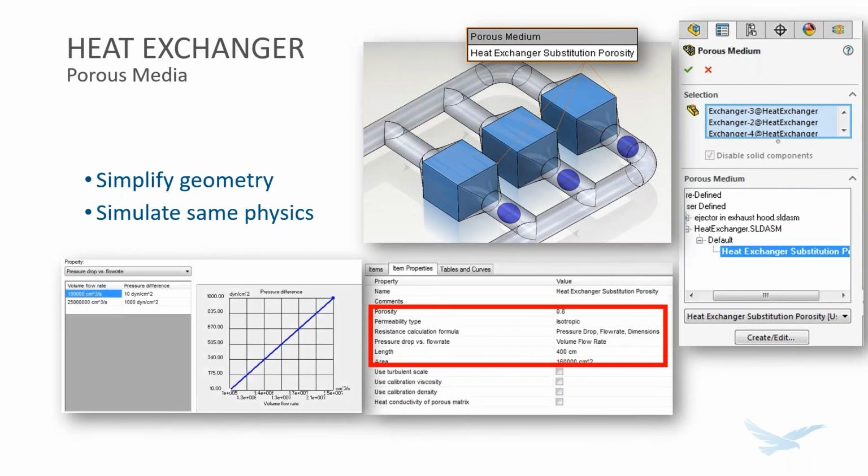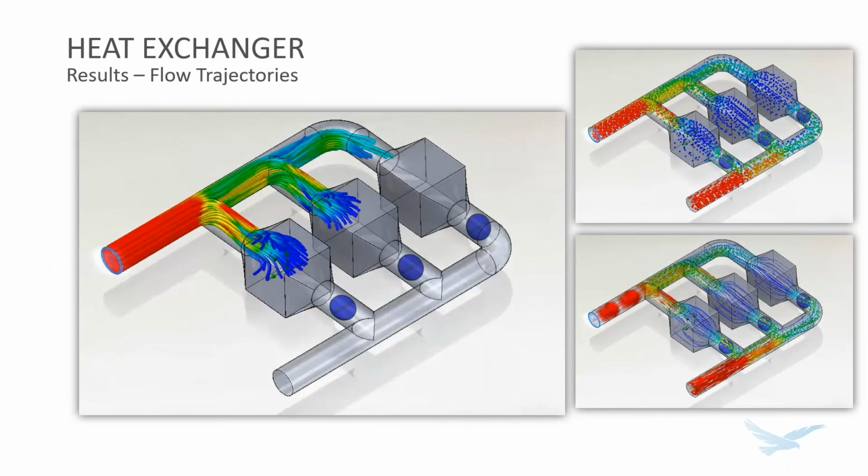So you've got an extensive engineering database where I can go through and define those porous media behaviors, things like a porosity value. Is it going to be sort of an isotropic or anisotropic behavior of fluid flow? That's all stuff that you can incorporate within those material models. So we've done what we need to here to define that as our engineering material.